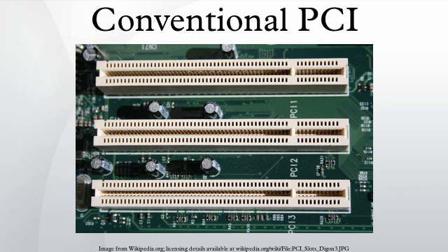0000, interrupt acknowledge. This is a special form of read cycle implicitly addressed to the interrupt controller, which returns an interrupt vector. The 32-bit address field is ignored. One possible implementation is to generate an interrupt acknowledge cycle on an ISA bus using a PCI ISA bus bridge. This command is for IBM PC compatibility. If there is no Intel 8259 style interrupt controller on the PCI bus, this cycle need never be used.